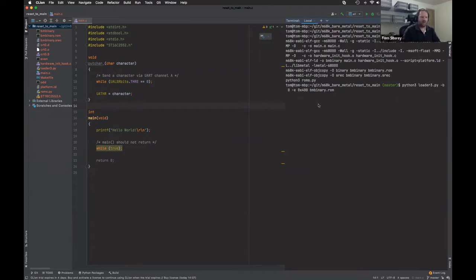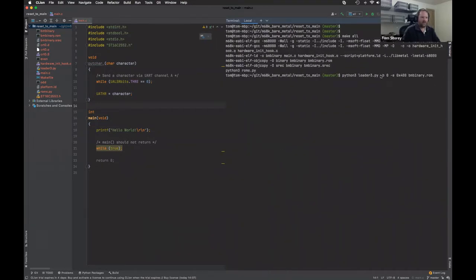So I run this script here, which will upload it to, you can't really see that very well, but it will upload it essentially to address 0. And then I'm going to tell my little monitor bootloader application to basically start executing from address 400, which is essentially what the CPU would have done with this if this code was programmed into ROMs.